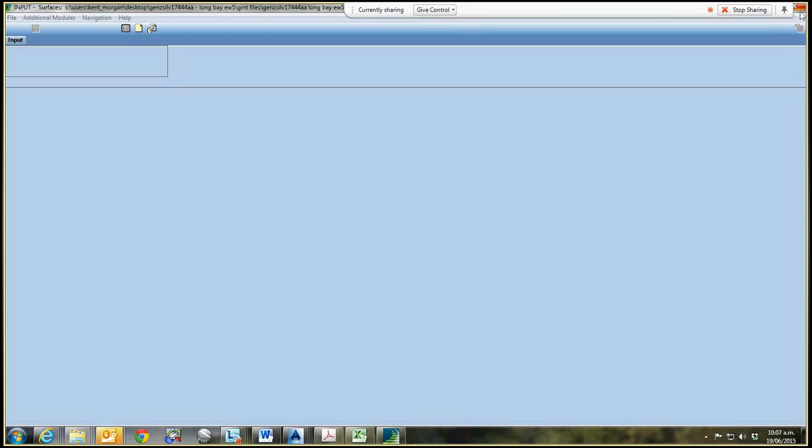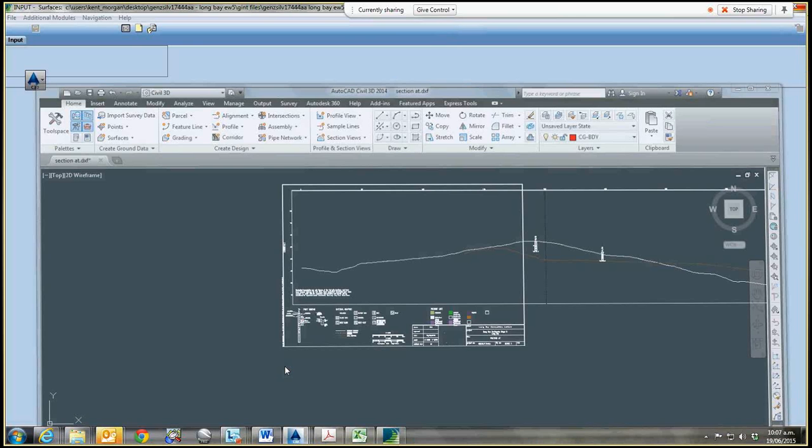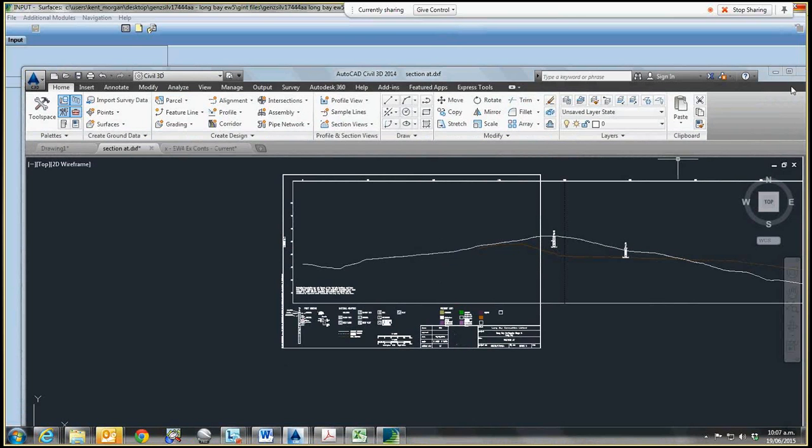Once you have your surface loaded, then you can go to the Output, the Fences tab, and export your cross-section. And then you can get it into CAD, and then you can do all your fine-tuning. So that's the gist of it. I'll upload all my notes and this video. And good references from here on out are Zach and Poi and Mohit.